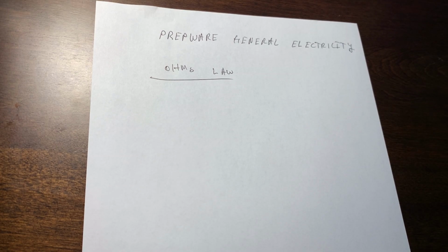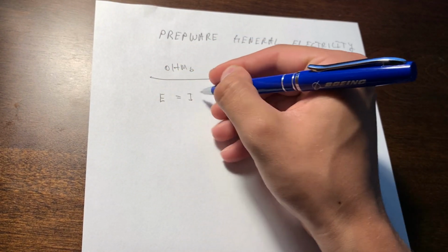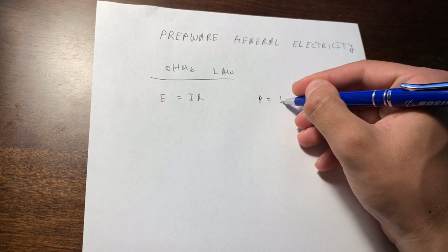In today's video, we will be going over some electricity questions from Prepware's General Electricity Study Guide. Most of these questions involve math and Ohm's law, and these are the ones I'm going to be focusing on. Ohm's law has two common formulas. They are E equals I R and P equals I E.